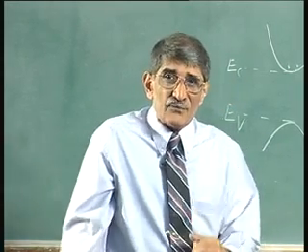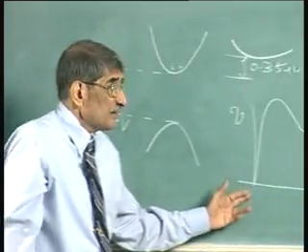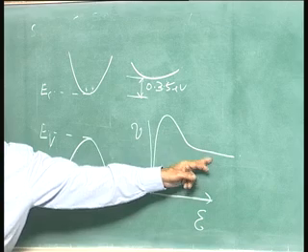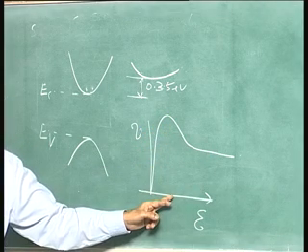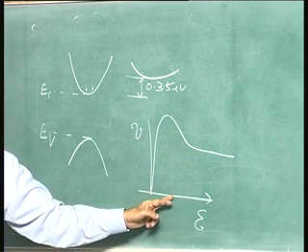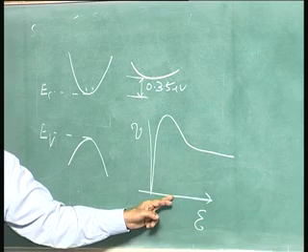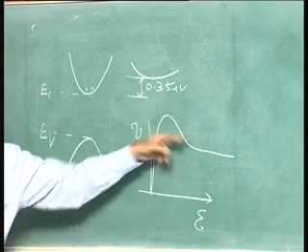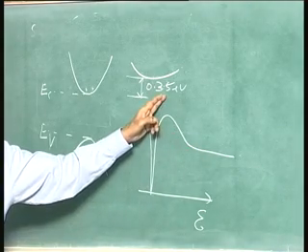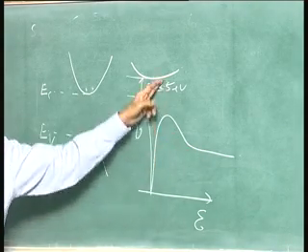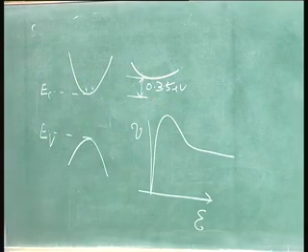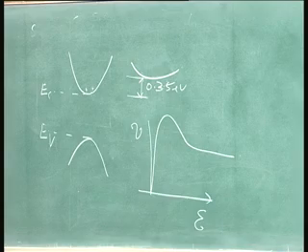The field is 10 to the power of 4, which is 10 kV per centimeter, somewhere there. This is 3 kV per centimeter. If you look at this entire static characteristic, you will think that is the velocity. But you are not going to that curve, you are still remaining in this portion of the curve. You will get decided by the slope, what is velocity, because electrons do not have that energy. This is the irony of the whole thing.